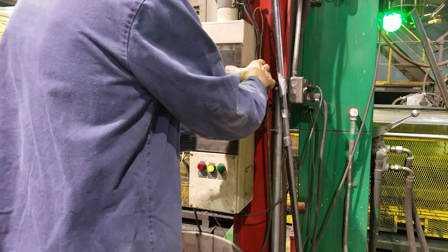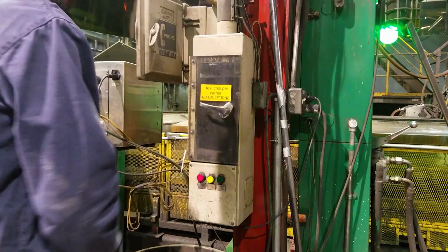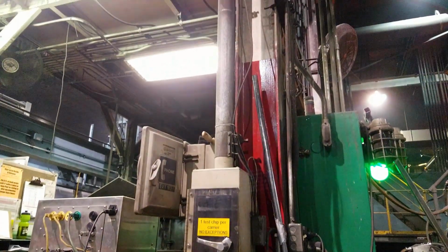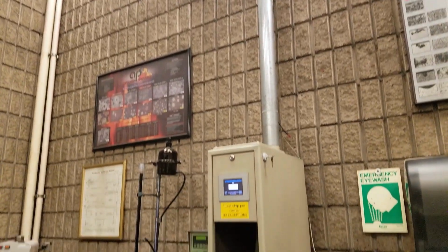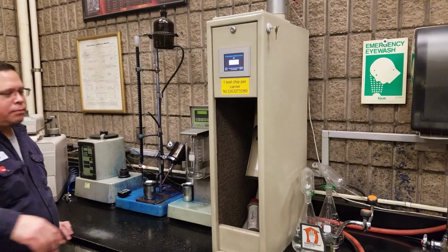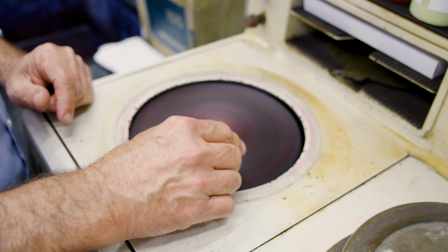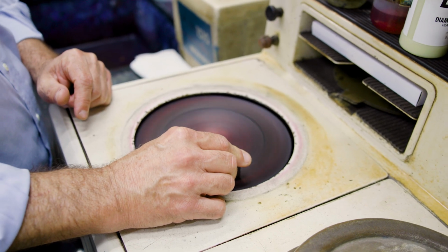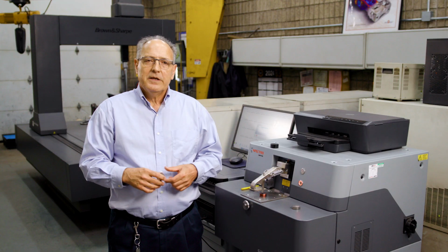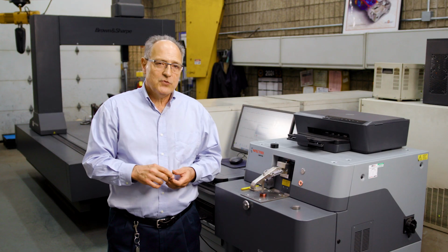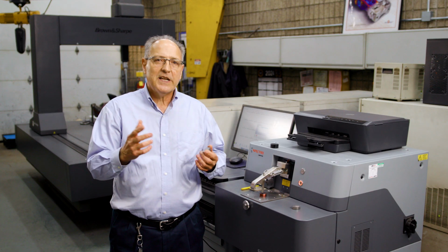All right, let's talk about chemistry control. We talked about the melt department guys pouring that little cup to check carbon and silicon. Well, we need other elements, so they're actually going to send samples to the lab. We grind the samples like this, okay? And we put them on this equipment that opens an arc like when you're welding, and that light, the spectrometer, is going to read 22 elements based on that light.